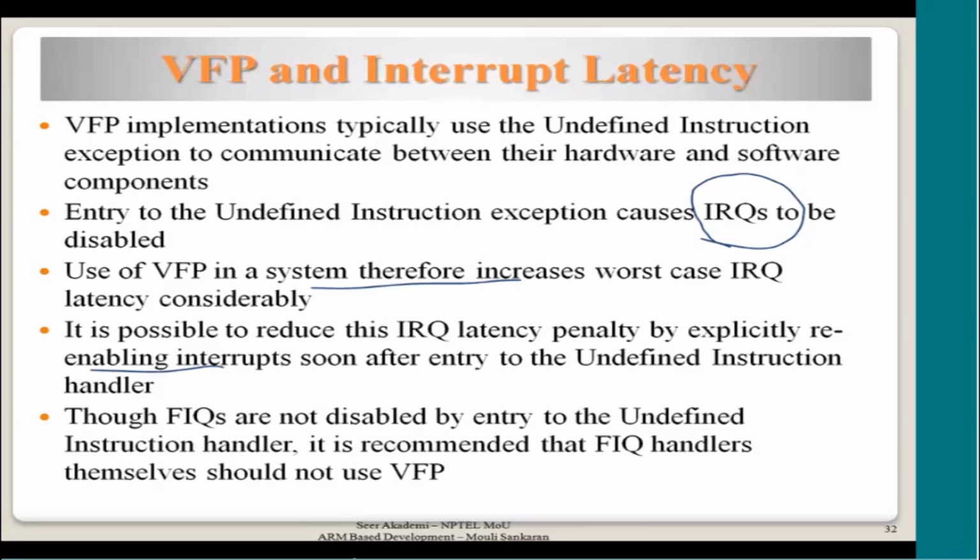Though FIQs are not disabled by entry to the undefined instruction handler, it is recommended that FIQ handlers themselves should not use VFP. What I mean here is that FIQ interrupts are not disabled even if undefined instruction handling of the vector processor instruction is running. If an FIQ interrupt happens during that time, it will be serviced because by default it is not disabled.